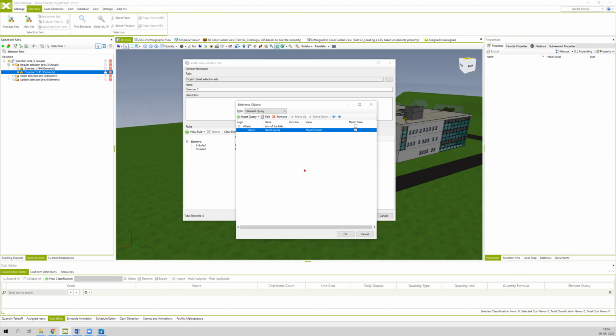And this is the reason why we will click on this rule, so it colors blue, with the right click, and a menu opens where you have the option modify, and then click on the option negate. So now you can see that the rule has changed, where we are looking for elements that do not have this certain property, which is called master format.